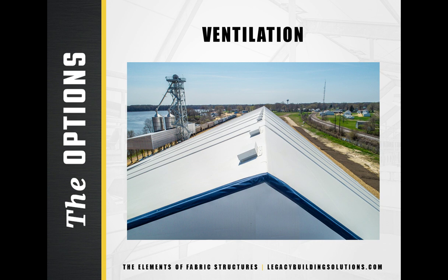All buildings need ventilation systems to provide fresh air inside the building and to allow the building itself to breathe. In many applications, a passive gravity ventilation system consisting of an intake system and exhaust vents will create an adequate flow of cool, fresh air.